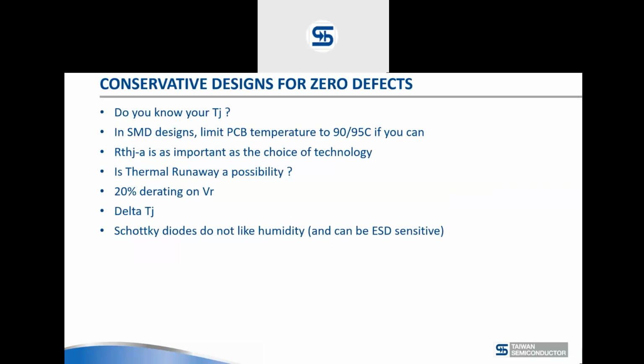Schottky diodes do not like humidity. So if you're working in a humid environment, potting might be advisable for you. And the small ones are also easily sensitive. So these are some of the recommendations we have for zero defects. However, unfortunately, what we have to say is that if the top priority of your company is cost, then nearly all the recommendations have to be reversed. So there is definitely a trade-off in Schottky technology. Not everything has to be reversed, but something has to be reversed.